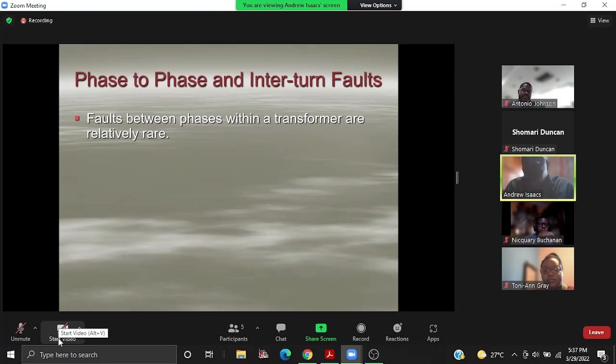Those big transformers that you see in the substation also have a laminated core. Unlike the little transformers that you would pick up and see the laminations, which are then glued back together, for those transformers, the core is bolted back together. So it's laminated but bolted.